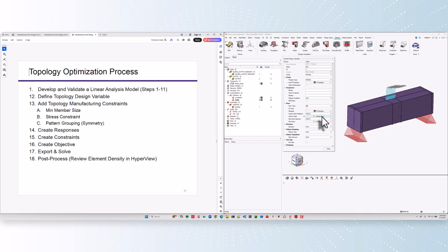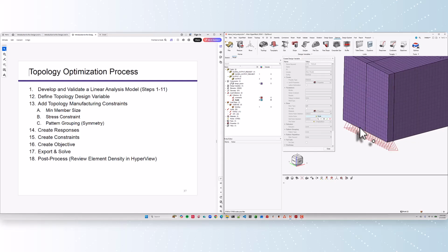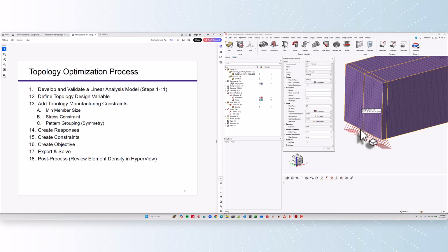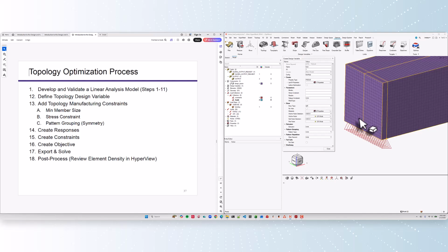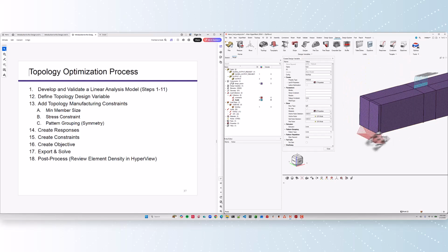And how do I define that? Well, I define a vector that defines the Y axis, right? A vector is defined by 2 nodes. So my anchor node is here, because it's right in the middle. And then I'm just going to go in the positive y-axis direction for my second node, and then I just pick the second node that defines that vector direction. Now the split means that it automatically created the negative one. Split says, okay, you define the positive one, I'll automatically create the negative one. And so I just defined that it has to whittle away material in the y direction.